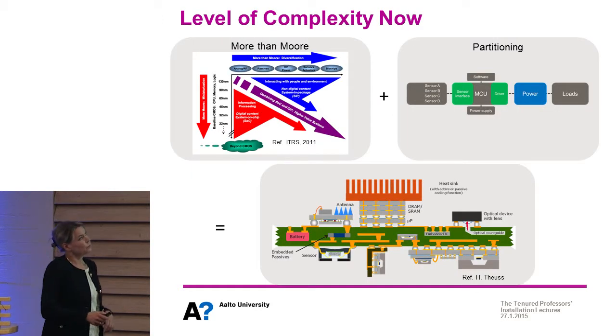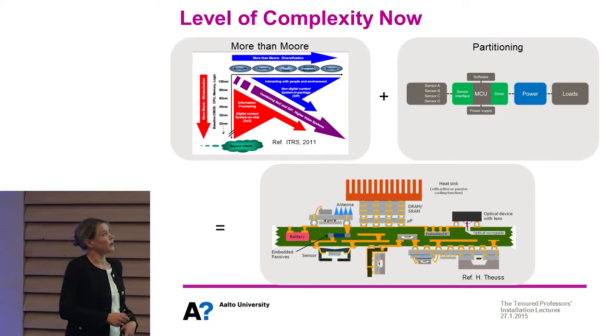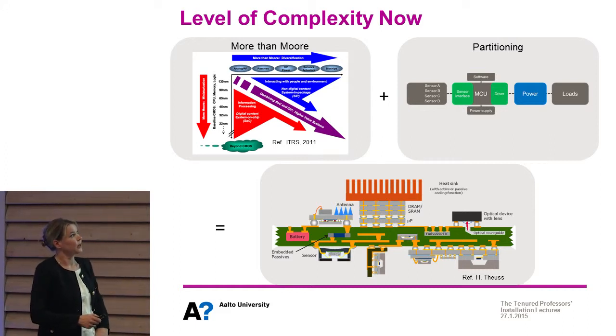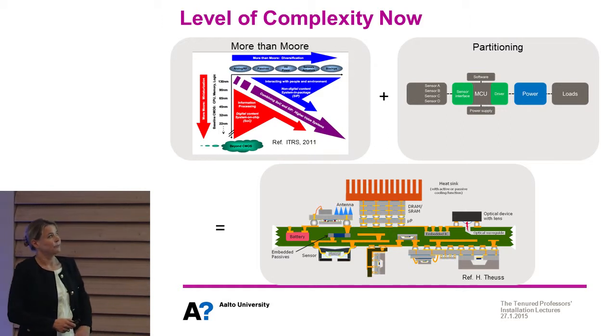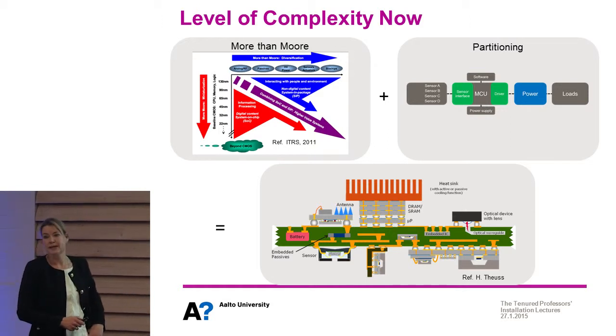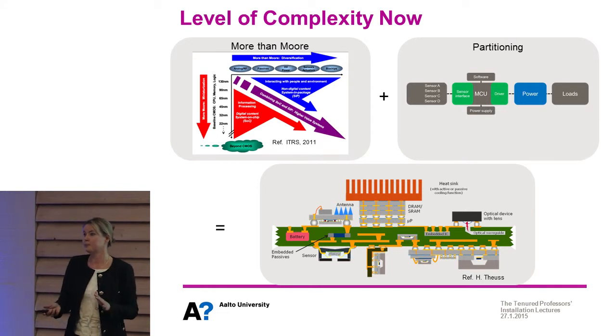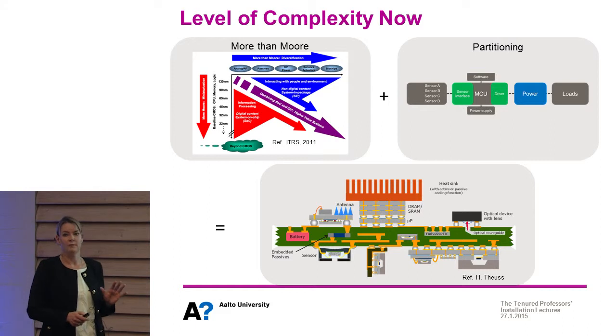So what is a microsystem? So we do have sensing functions, we do have some analyzing, processing functions, we do have some actuating functions, and depending on the application, these will certainly be distributed differently, but quite seldom can all of them be integrated monolithically. That means within one piece of silicon or another semiconductor.